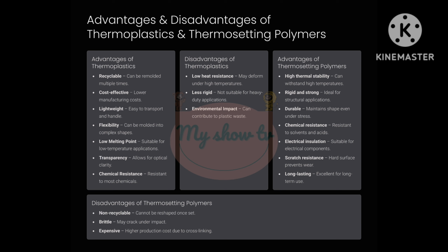1. Advantages of thermoplastics. Recyclable, can be reheated and reshaped. Cost-effective, economical for mass production. Lightweight, suitable for transportation. Malleable, easily molded into complex shapes. Good insulator, effective for electrical insulation. Transparency, allows optical clarity for certain products. Chemical resistance, resistant to various chemicals.